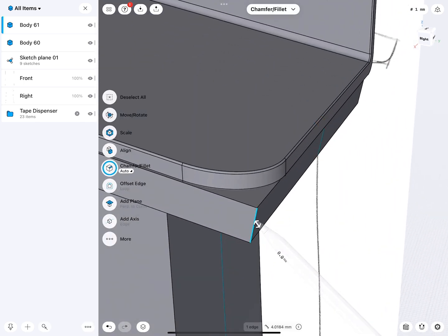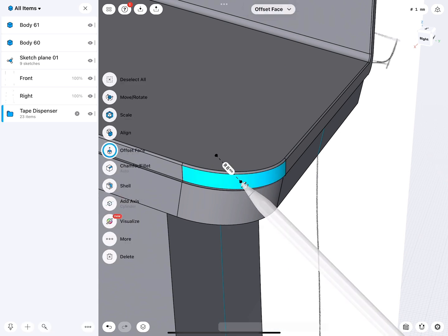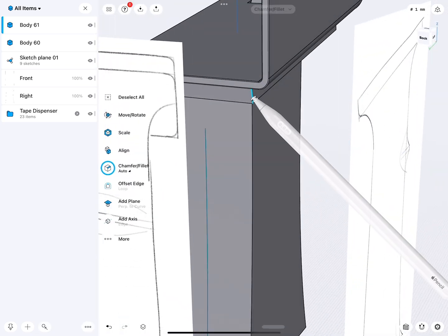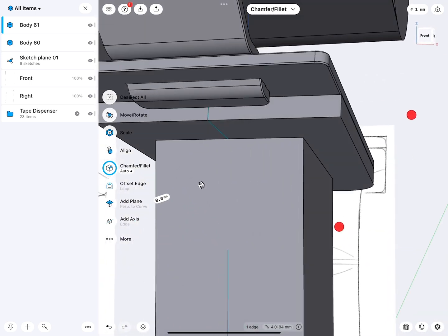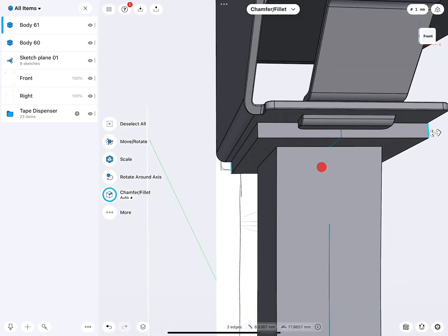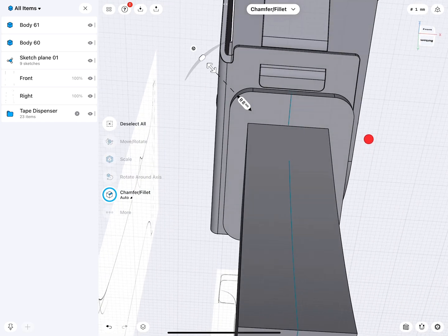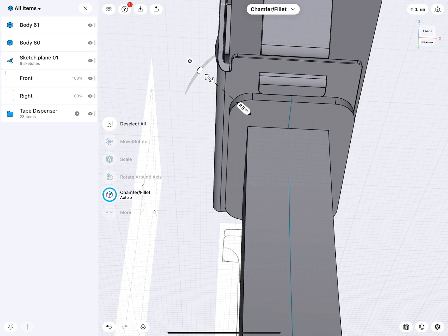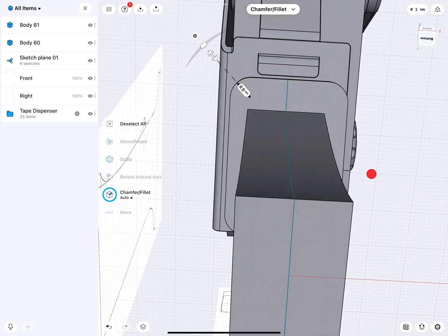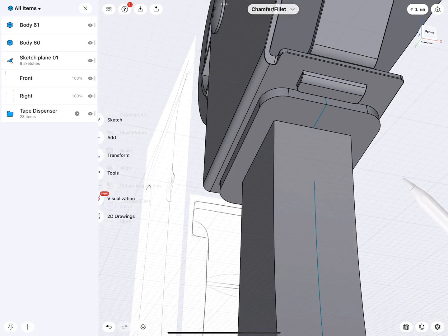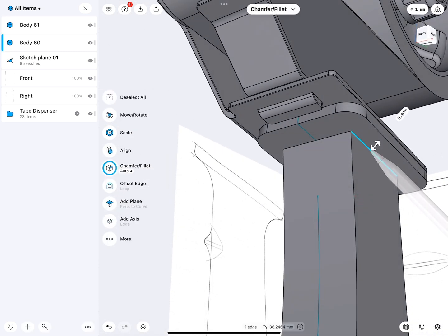The socket is pretty easy, or the base, so we can adjust the edge roundings. You see here 8 millimeters and 8 millimeters. I just made this the same. Very good. And to be consistent, I will now do this on every edge. There we are. Very good. If I take a look at the sketch now from here, I can see that from here to here, this distance is probably a little bit different than there.